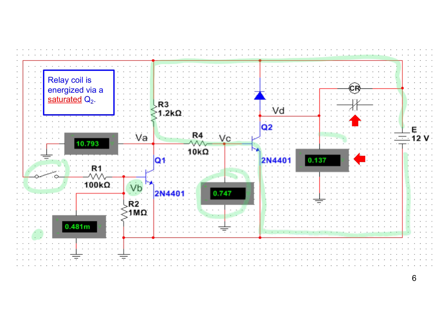And again, this is the Q2 saturation voltage. Note, in a practical transistor, you're never going to make that zero. So that's right in the expected range of 0.1, 0.3 if it's fully saturated. And there is a current path then going from here, like there, down, and then back, just like that. Okay. All right, and of course that's being held closed. Right. So the relay coil is energized via Q2 being saturated. This one here is in cutoff.